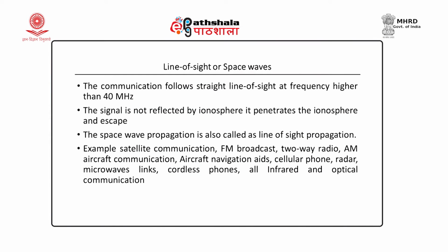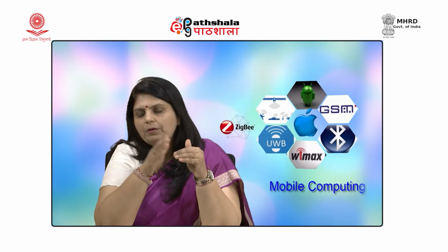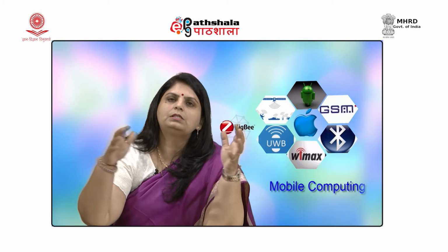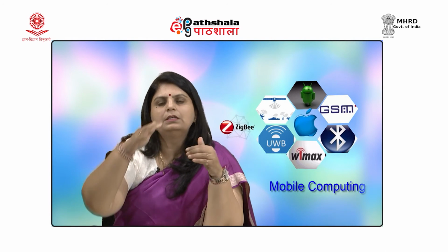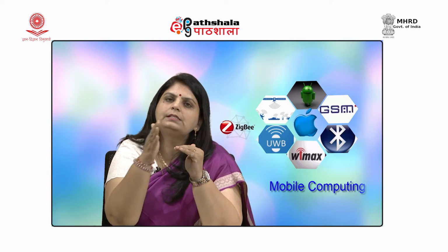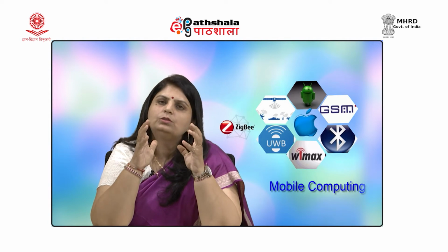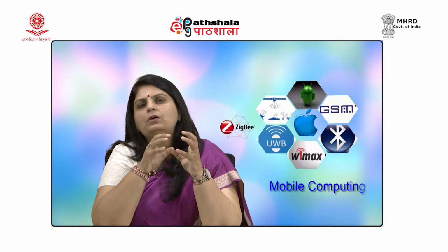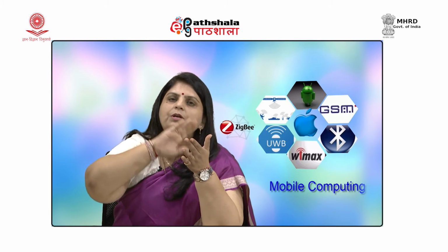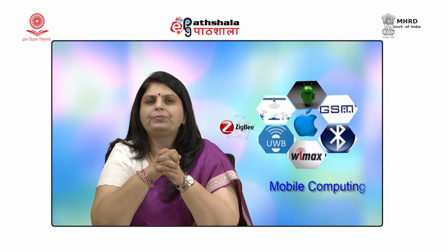Now, we have talked about two types of propagation. At a certain frequency or below a certain frequency like 2 megahertz, the waves have got such a big wavelength, they are travelling along the ground. Now, as I shift towards a little higher frequency, I just learned that those high frequency waves have got the capacity to bounce from the atmosphere. That is, they will not be scattered by the atmosphere, but they will reach the ionosphere.